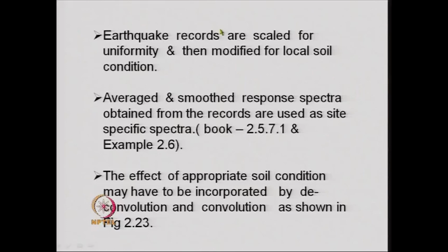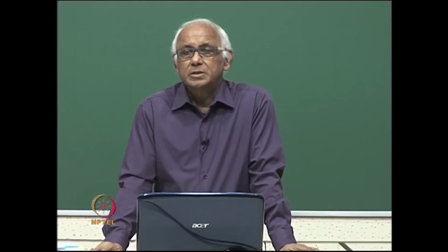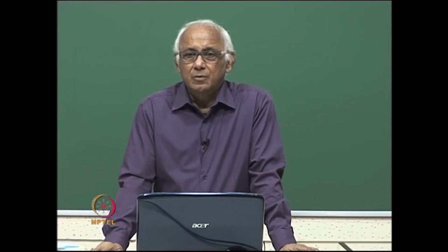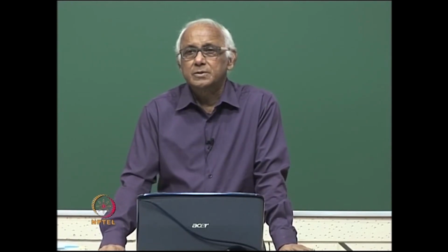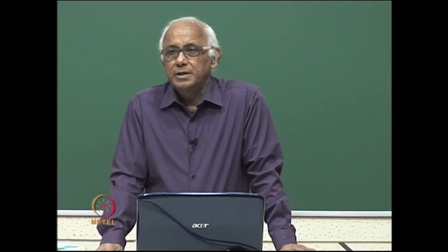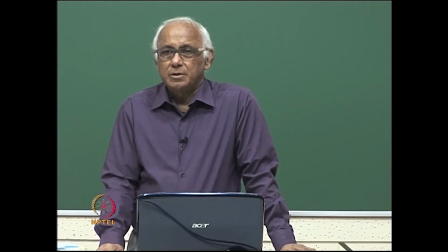Once we have collected enough earthquake records in and around that site after augmentation, then we scale the earthquake records and also modify them for the soil condition.